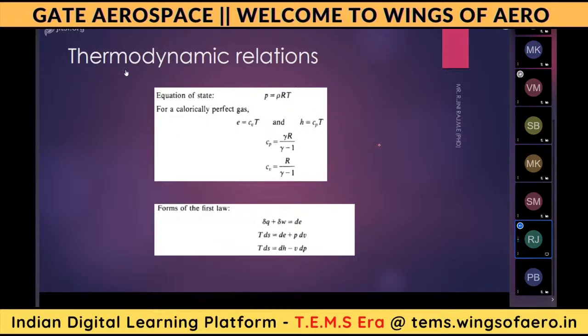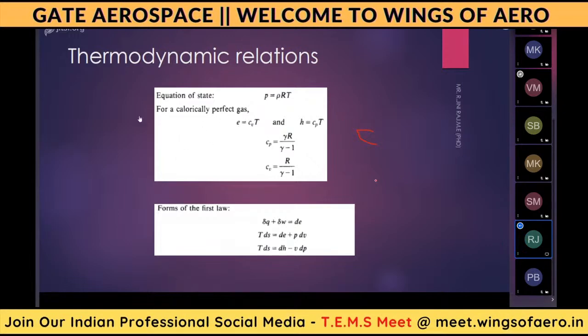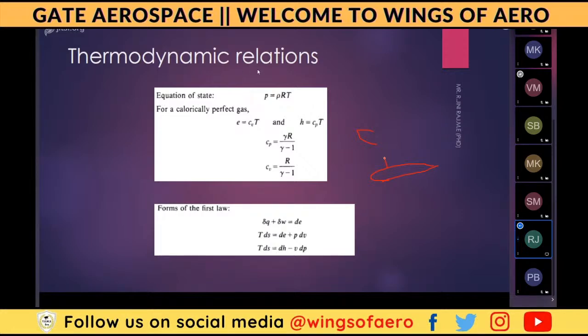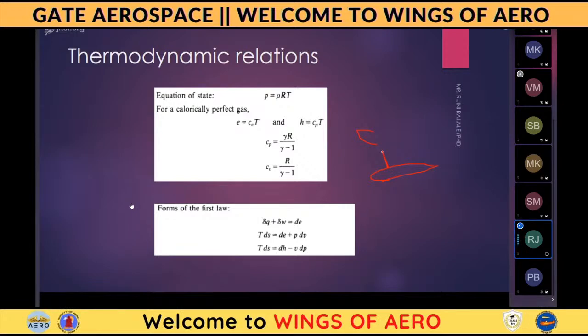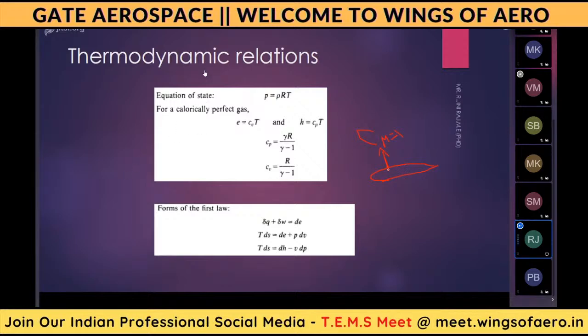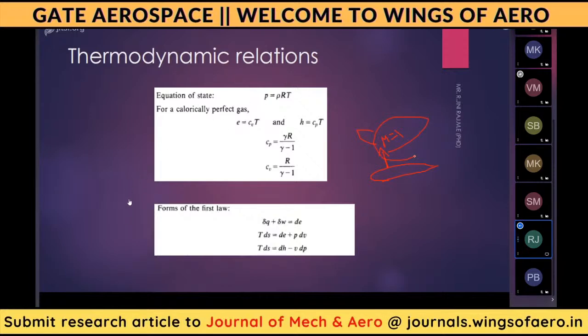See, this is the airfoil. So in normal aerofoils, if we are approaching Mach number M equal to 0.8, then over the surface of the aerofoil at some point we will get M equal to 1. This is called critical Mach number. But this will increase the drag. That is drag divergence Mach number and all. It increases the drag of the aerofoil.